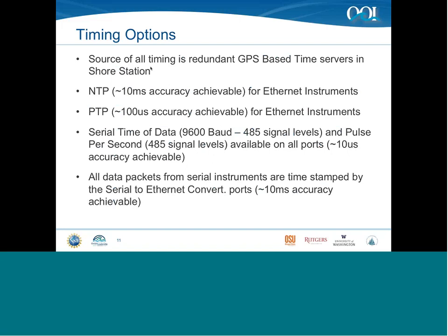Any serial instrumentation is going to have its data timestamped in the junction box to about a 10 millisecond accuracy. So it just depends on the time that that data packet reaches the junction box, and then that data is all pushed ashore. We also have 1 pulse per second signals and NMEA time strings that we can push to instruments on the cable.